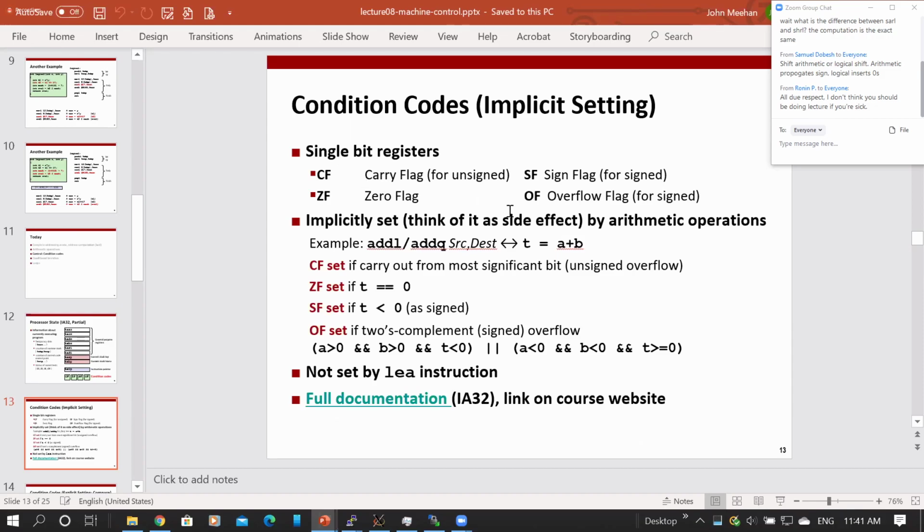Lighting up the carry flag or the overflow flag, saying, which way do you want to interpret what those things were? I don't care. It's all bits to me, right? Anytime you do an operation that resulted in the value 0 sitting in some register, the 0 flag gets lit up. So if I did a move long word from some memory location into some register and the value that I moved in there was 0, that would light up that condition code.